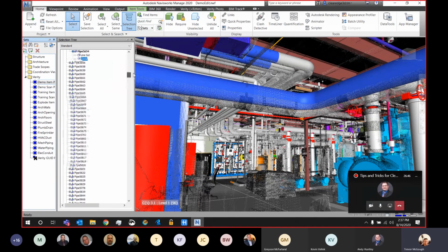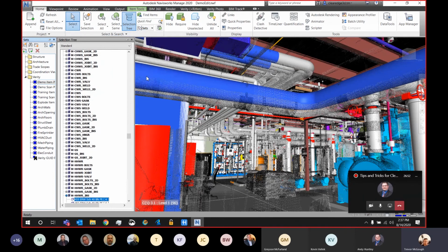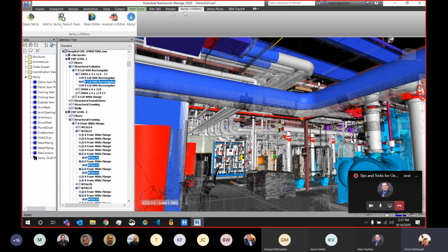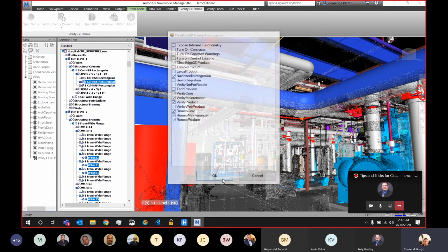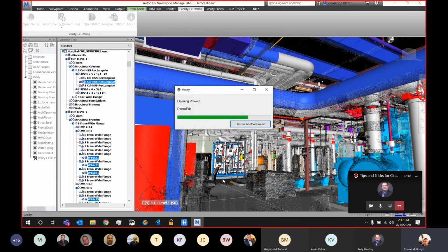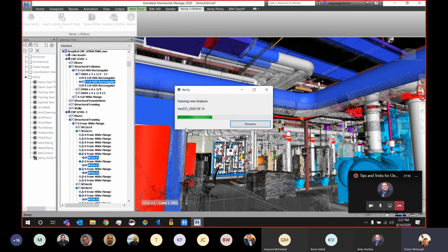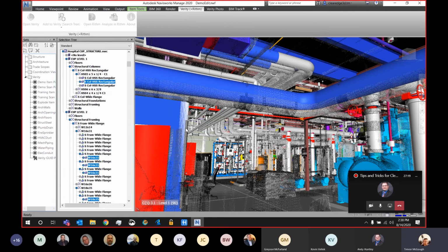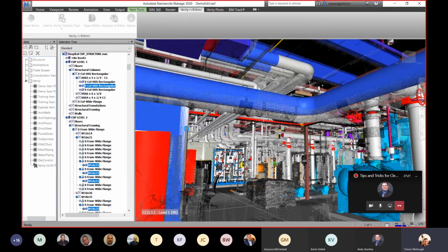Another key pro tip that I always like to tell people, especially for larger projects, is to do a little bit of QA/QC of the item set that I bring in. For example, a lot of brand new Verity users will plop in the whole MEP model. So not only are they getting the major pipes, but they're also getting the conduits and the smaller objects, maybe stuff that we're not really interested in inside of Verity. A good one for the steel is if people bring in the steel model, not only are they going to get the major I-beams, but they'll also probably get the plates and the bolts. Again, that little stuff that we're not really interested in, I guess you could say.